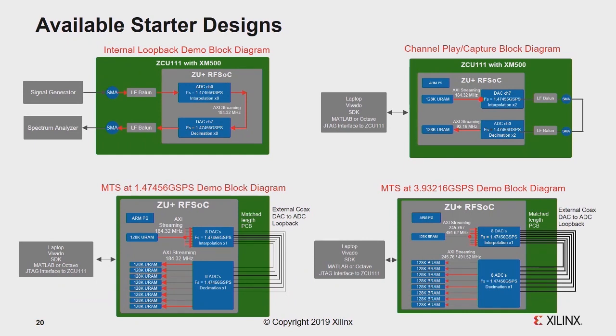There are 4 designs available right now. We have a send something in, get it back out design. You can load something into a buffer and transmit it out of a DAC. You can do a loopback and see it in the ADC. There's also what we call MTS, or multi-tile sync, the ability to sync all the DACs and the ADC channels.